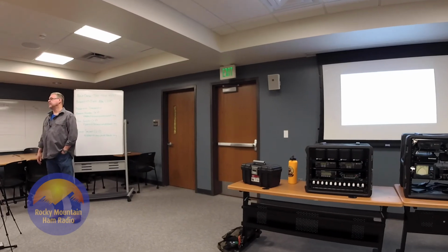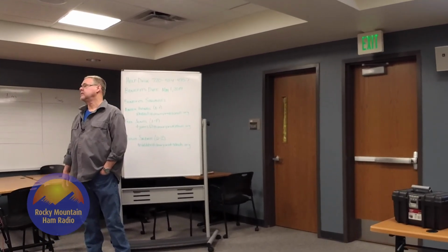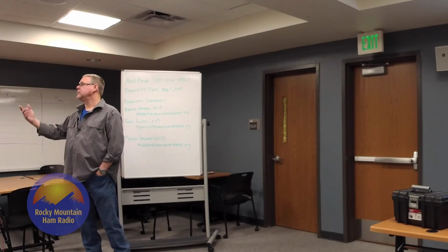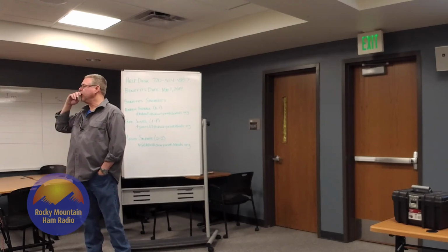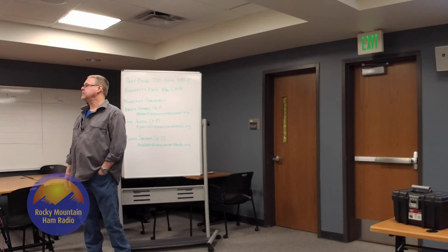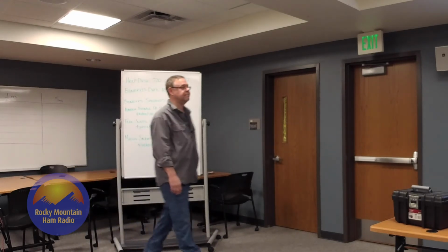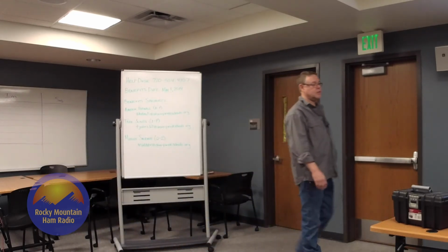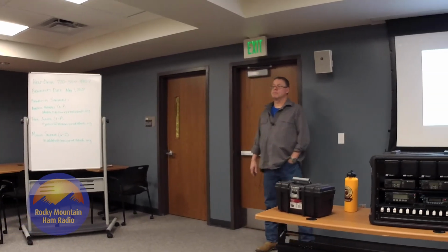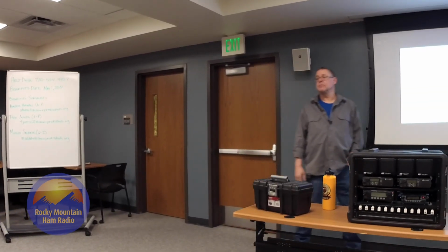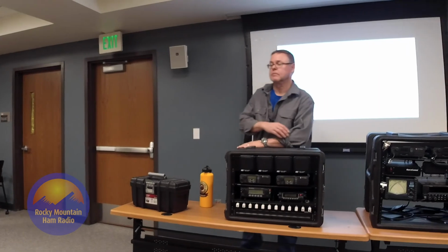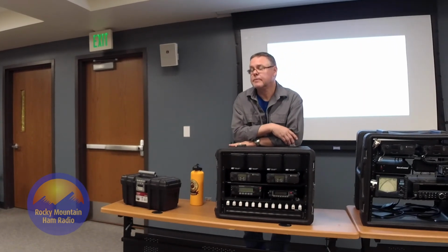What size is your generator? Your gen set? Kilowatt generator, but I oversized it for putting on a real generator someday. No, what's the one you have now? I was just curious. Oh, it's an IQ 2000. Okay. They're nice in the sense that they'll throttle down, so they'll run at a low RPM, so the gas will last forever. And the inverter basically puts out 60 hertz, and because it's not a sine wave, it's just noisy as hell.